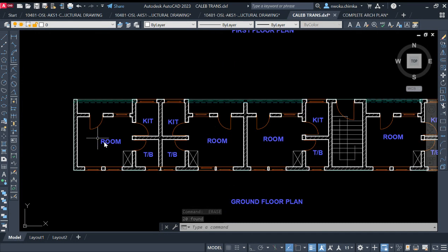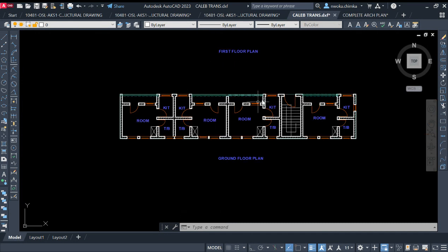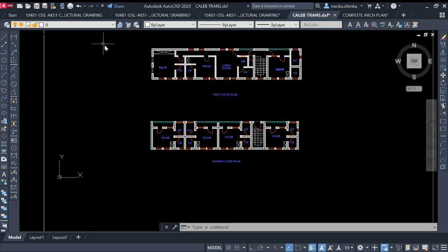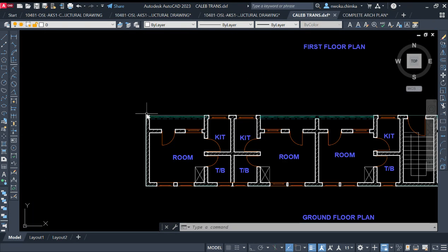So right now I have to perform my GA drawing. GA drawing simply means general arrangement drawing, which means to place your column and your grid. So if you want to export your plan from AutoCAD to Protastructure, there are two layers which you are meant to create. Without those two layers, Protastructure will not be able to see this drawing and also see the column point as column, or the grid line as axis.